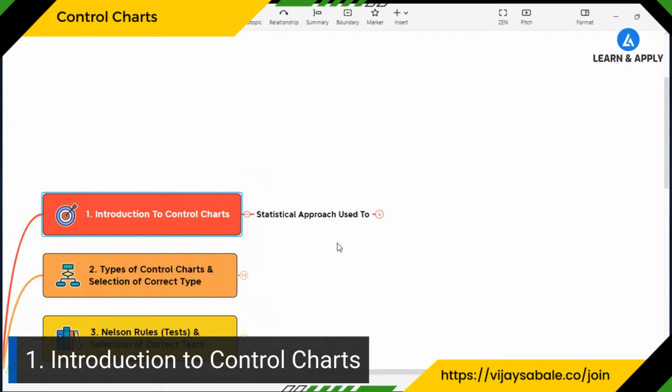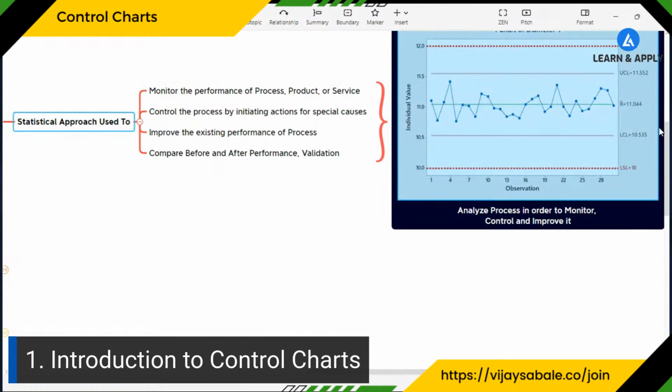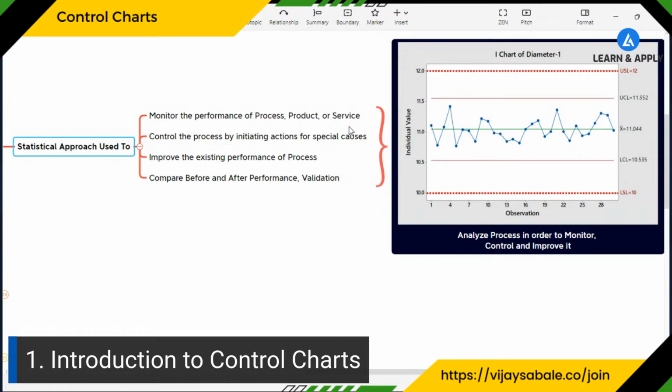This is the statistical technique, the statistical approach, that every working professional is using in their day-to-day or professional life. And what is the intent of that? That I'm going to explain. The control chart is a statistical approach which is used to monitor the performance of your process, product, or services. It is also used to control the process by initiating actions for special causes. That means with the help of a control chart, we are going to understand whether the variation in our process, product, or service performance is only due to the normal causes or is due to both normal causes as well as special causes. If it is due to special causes as well, then we are going to detect that and take actions on them. We are going to remove them so that we can improve the overall performance of our product, service, or processes.